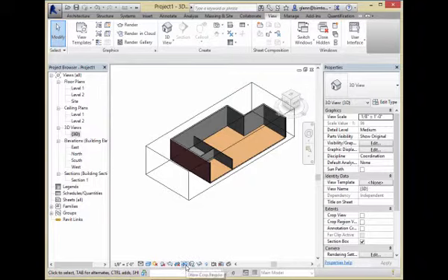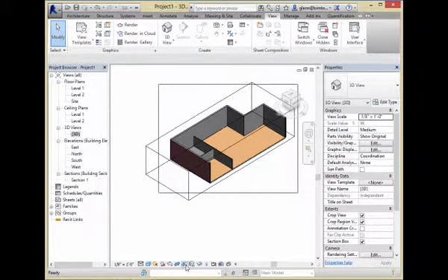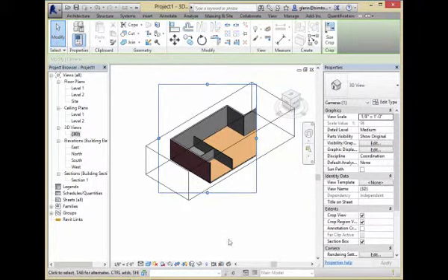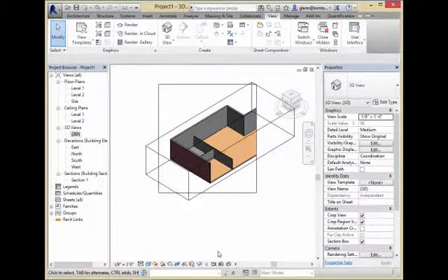And how I do that is let me show the cropping region. So there are 2 different regions, they kind of overlap and look strange, but this is actually the boundary which will be printed on the sheet. So although I've sectioned it here, if I bring in the crop region and cut off some that way, you'll see it's kind of a weird thing. Part of the model is cut away, exposing the innards because of the section box. I cannot see the rest because it got sliced off the side of the view by the cropping region. Those 2 things are confusing. They're very parallel, but they really control 2 different aspects. Does that make sense, Lottie? Okay.